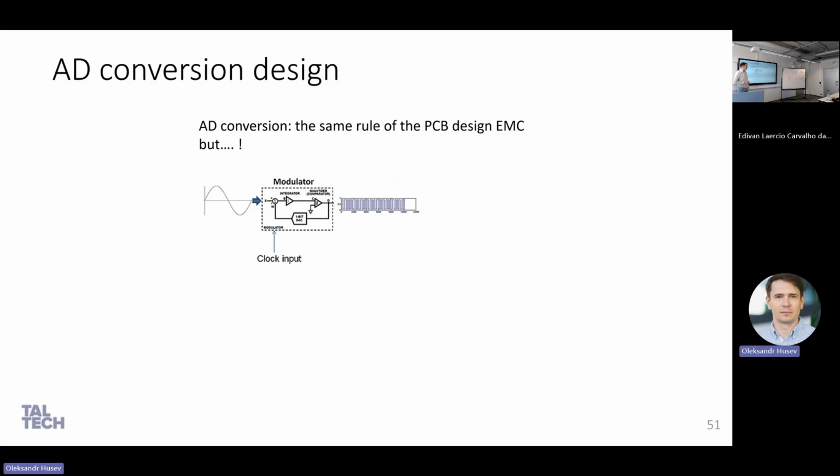I don't know any design that doesn't have this as well, because if you want to make a cheap product, by default, you must consider this. Usually it should be a single PCB, because the PCB itself is not very costly, but assembling is more costly and so on. So one product usually must have a single PCB which contains all parts, including control, measurement, and power part, right? And the problem is that you have, of course, low frequency signals and high frequency signals, right? But now we will talk about grounding and different grounding approaches.